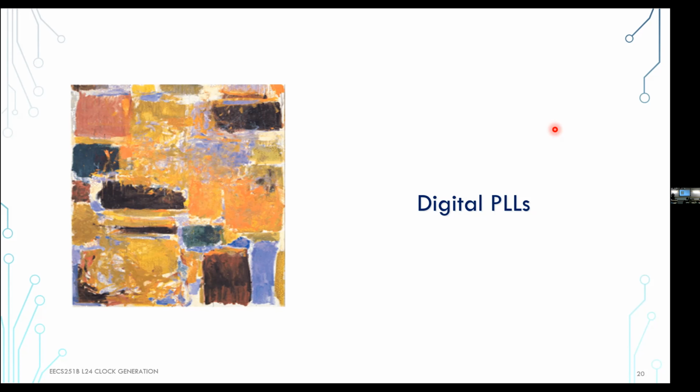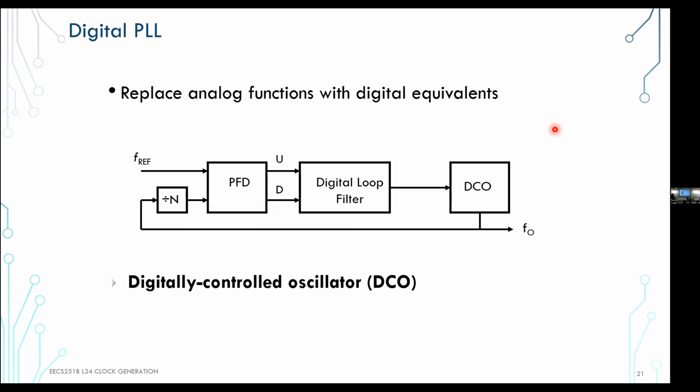And if we already looked at the reference clock noise analysis, the loop kind of tracks it. So if I can characterize what that quantization noise is that I'm injecting into the system, I may be able to manage it.